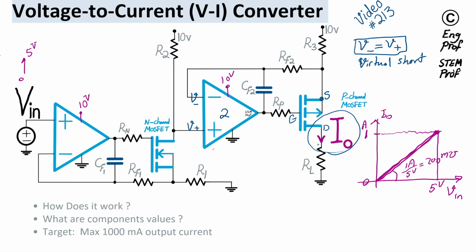As I said, for maximum Iout, we have 1 amp current that is going through the source-drain of the PMOS transistor. So I'm going to refer to that as I_SD PMOS max. In this case, we are saying it's 1 amp. Just bear in mind that in this circuit, obviously, the PMOS is bearing the main responsibility of high current delivery to the load. So the PMOS needs to be selected properly as a power transistor with, let's say, at least the minimum continuous current tolerance of 1 amp. So when we select this from DigiKey or Mouser, it's better to shoot for a current max of, say, up to 2 amp or in that ballpark, so that we protect this transistor.